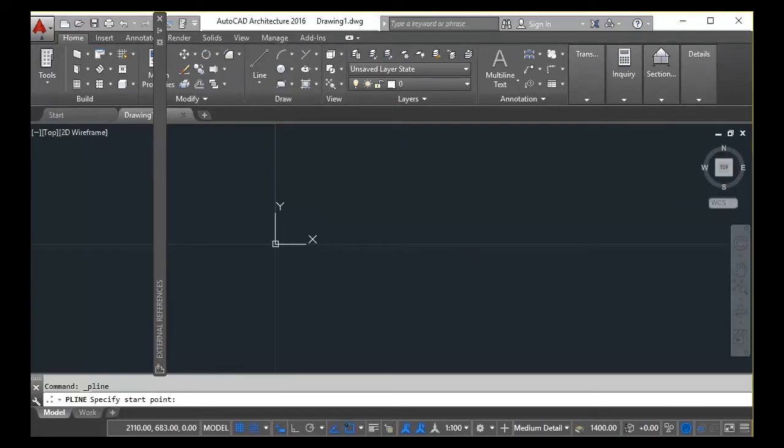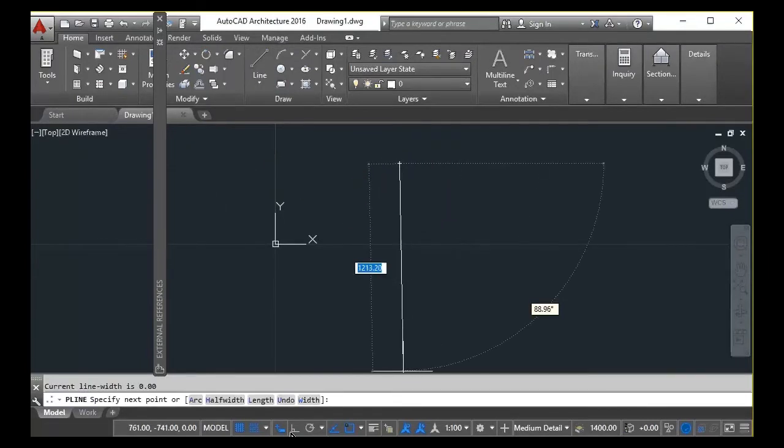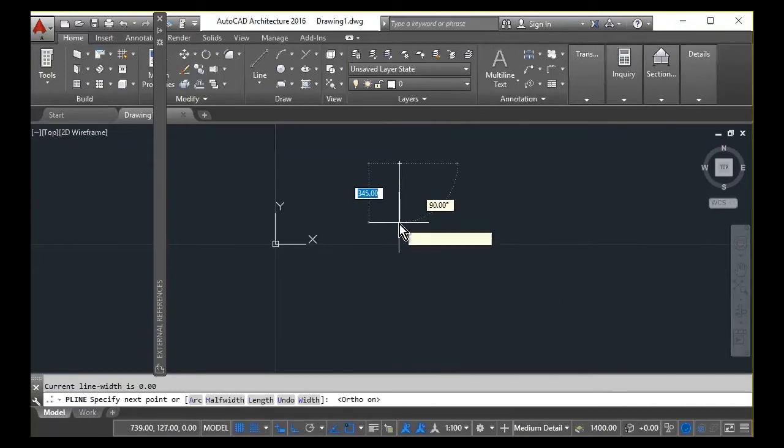Now let's convert that to metric. That will roughly be 25 millimeters tall and 100 millimeters long. So we're going to use the polyline, and we're going to draw the first line. I'm going to turn on my ortho so I get these lines straight.